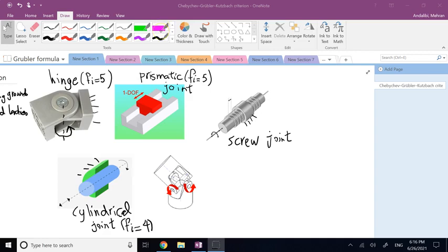So basically, if you rotate this bolt by 2 pi radians, then the amount of advance is what we call P, or pitch. That's the pitch of the thread, which is the distance between one thread to the next. That's all it can go forward and backward. So you see, one motion does depend on the other one.